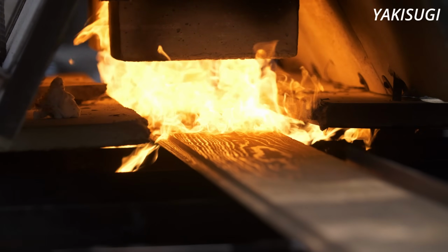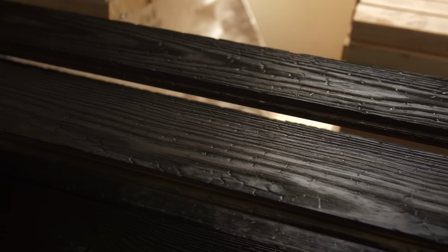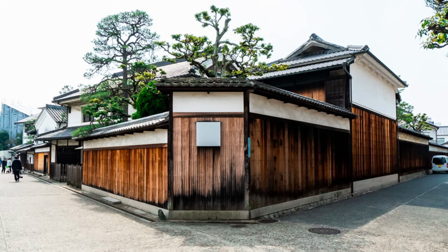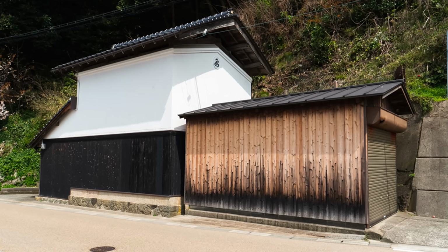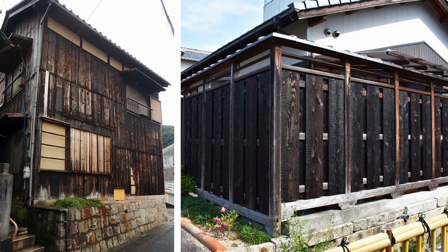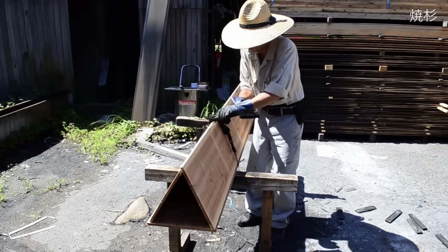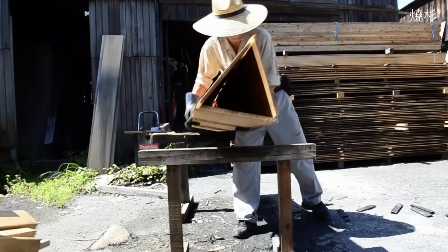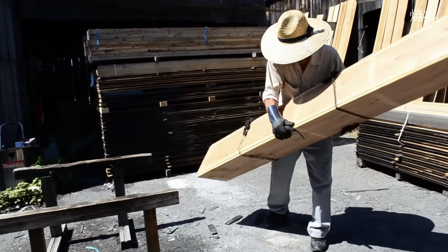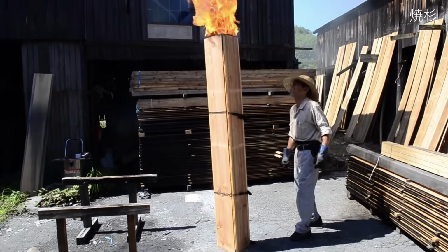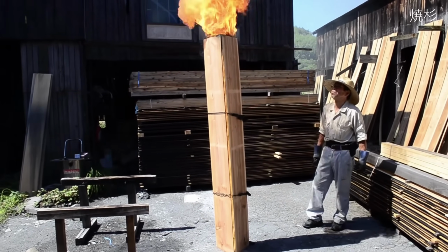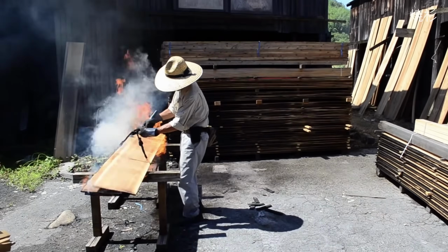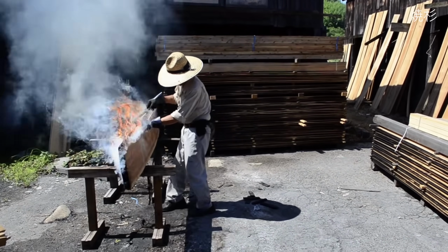Yakisugi is an ancient Japanese architectural technique that was used to preserve Japanese cedar or sugi wood. It was invented in the 1700s when the durability of homes in remote areas became a major concern. Three wood planks were tied together lengthwise with string to form a triangular tunnel. Tinder was stuffed into the center of the tunnel and lit on fire. When flames poured out of the top and all the interior surfaces were scorched, the flame was put out with water. This process removes both free and bound water inside the wood.